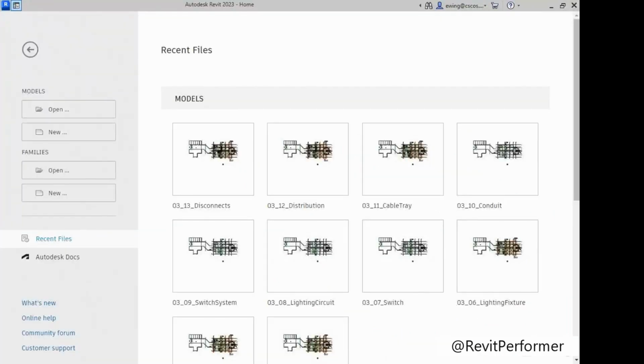View templates in Revit give us the ability to control the visibility graphic overrides of multiple views globally. Most views in Revit are only to show certain elements. For example, a power plan should not have lights showing up. Lighting plans should show electrical fixtures and mechanical equipment. So the objective of this video is to create some view templates and apply them to the appropriate views.